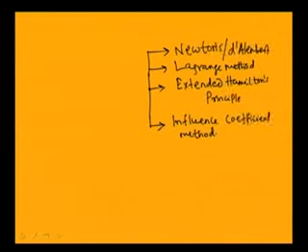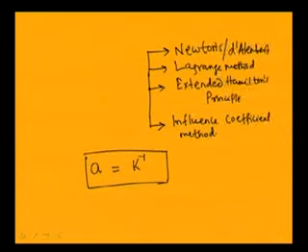You can observe that the displacement flexibility coefficient matrix equal to 1 by k, that is the reciprocal of the stiffness matrix. So, this is equal to k inverse. The displacement influence coefficient matrix and the stiffness influence coefficient matrix are related by this formula, and by finding either one can write the equation of motion as m x double dot plus k x equal to 0.